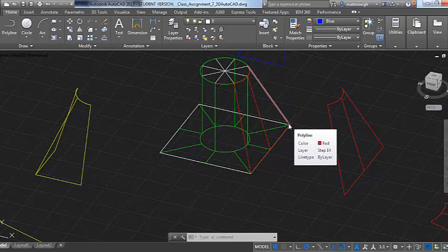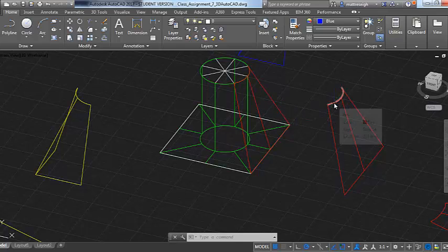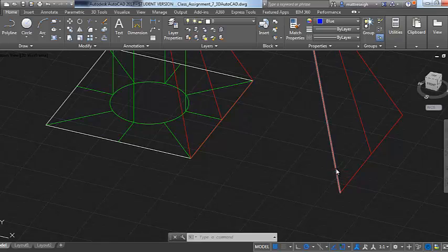And I would get that press brake look from those pictures that we started with. But essentially from the center down, I would split that in halves around this top here. Half would go down to one corner, the other half would go down to the other corner. The disadvantage of this is it puts a little bit of work on the fabricator because this is going to flare out a little bit.